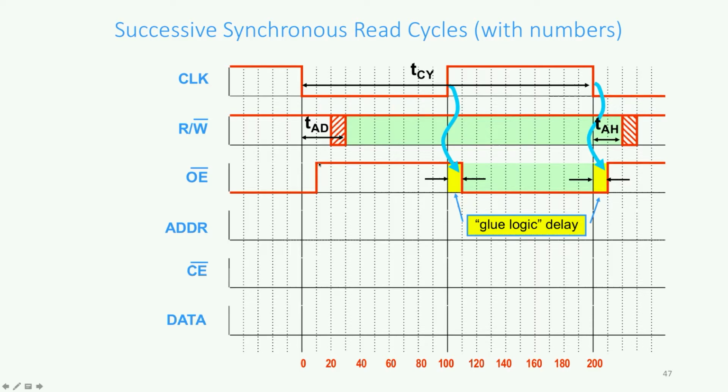So that's the least interesting part of output enable. Output enable stays where it was for a longish period of time. Then the important part is over here, where the clock signal transitions again, and output enable is going to change to a low state, but it has to wait that 10 nanoseconds again, because we're assuming that the clock changes, and then 10 nanoseconds later output enable changes to the correct value. Now it's held stable, and on the other side the clock changes again, and again you've got that 10 nanosecond delay. So that is the glue logic delay.